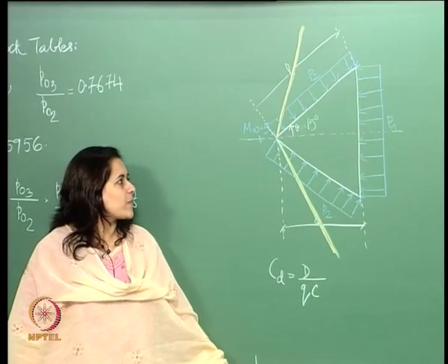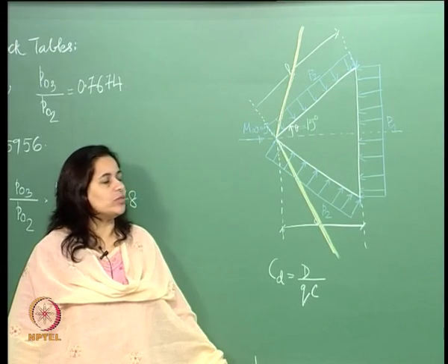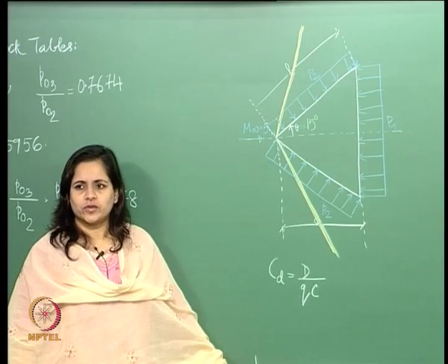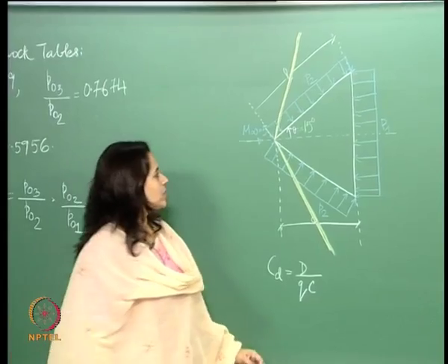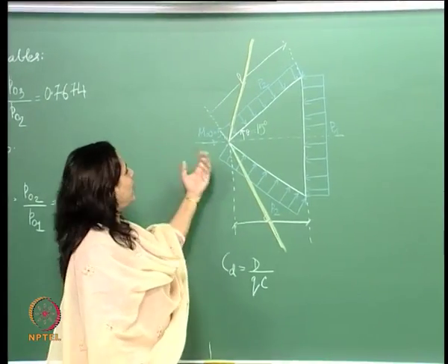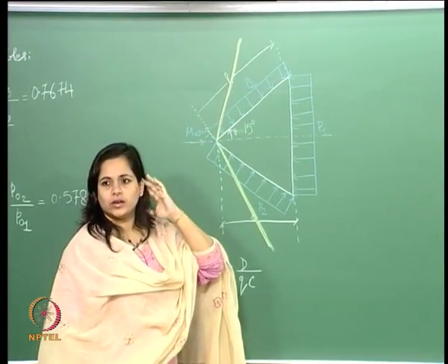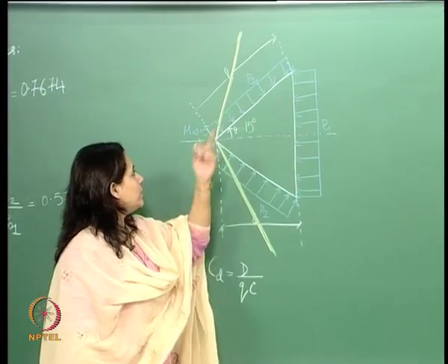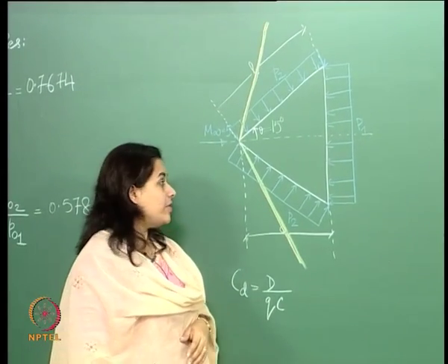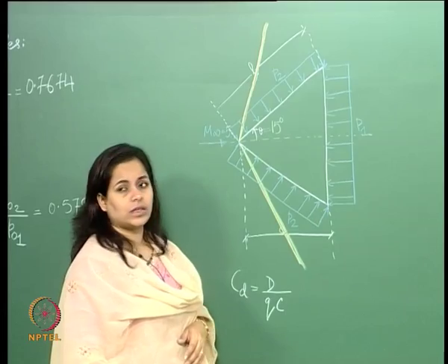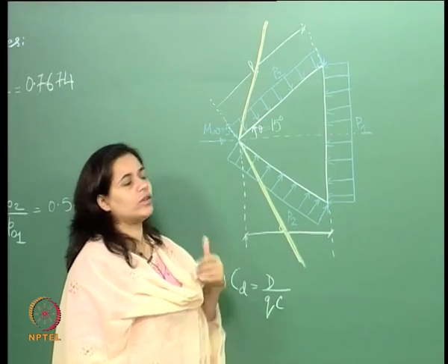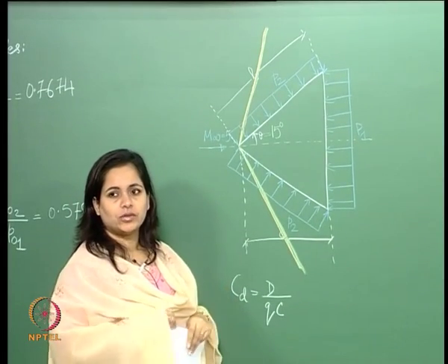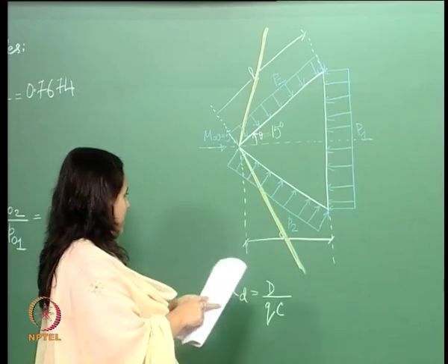So this has a certain pressure distribution, and I need to calculate the coefficient of drag. I can always calculate the drag if I can get some value for this pressure distribution. In this case, however, it's not that simple, because we might have a shock wave here. So let's see how that comes into play.